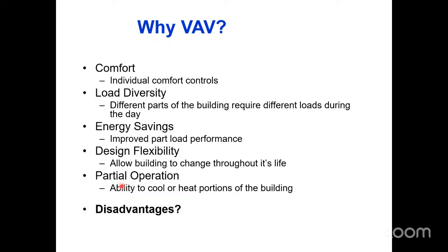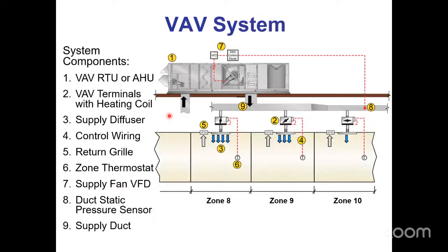The people in the middle do not need any heating at all. It's cooling only all the time, year round. When it's negative 23 degrees, cooling. When it was polar vortex, negative 27 a few years ago, we had people calling to complain that their chiller wasn't running. It had never been negative 27 in our lifetime around here, so we didn't think about it. But their chiller actually shut down, and they had no cooling in the middle of the building when they needed cooling, because year-round, you need cooling in the middle of a large commercial building. So this air handler is providing 55-degree air down the duct all the time.